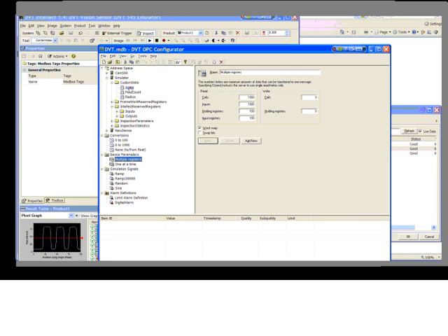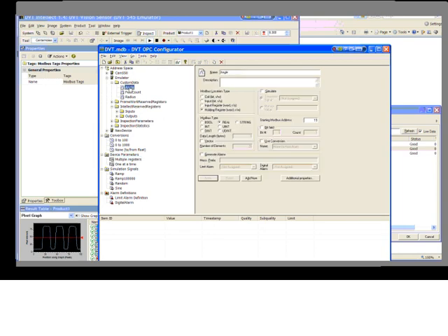And the other couple of points is that when you configure a custom data item on the OPC configurator, those are not automatically detected. So the DVT OPC configurator doesn't automatically detect Modbus tags that have been set up through Intellect or Framework. You have to manually add them. You have to specify the starting Modbus address and the data type. Once you remember those key issues, everything should be pretty straightforward.